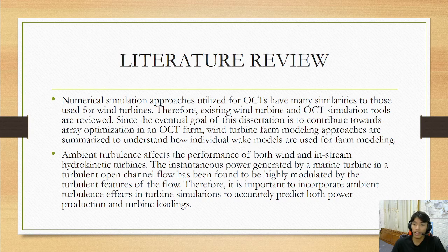Ambient turbulence affects the performance of both wind and in-stream hydrokinetic turbines. The instantaneous power generated by a marine turbine in a turbulent open channel flow has been found to be highly modulated by the turbulent features of the flow. Therefore, it is important to incorporate ambient turbulence effects in turbine simulations to accurately predict both power production and turbine loadings.